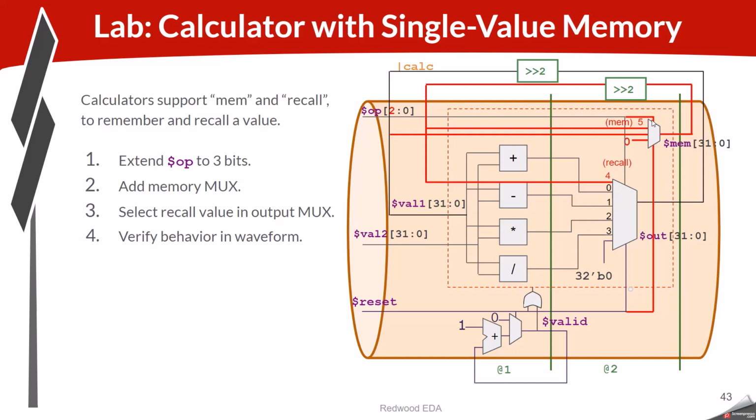Just a little bit more about the recirculating mux on state. Assuming we had done this with a 1-cycle loop, generally in Verilog when you're coding, and this course isn't about Verilog, but many people I'm sure have seen Verilog before and are used to it, you tend to provide code that's going to update the state only when there is an update to the state. In TL Verilog, I think it's a bit cleaner to be explicit about the values for all cases. So we're generally explicit about the recirculation path, which implies this recirculation into a mux.